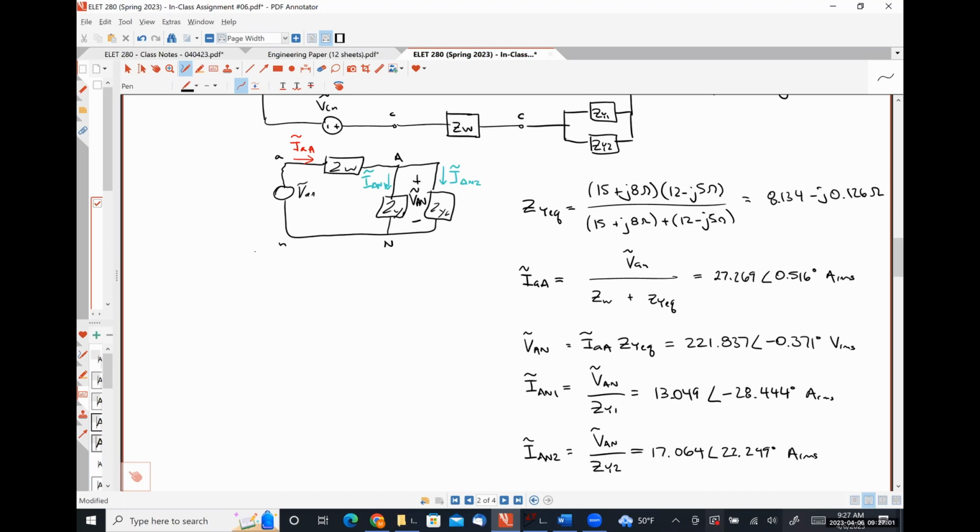So in order to solve for the phase currents in the B phase, what would I do? Subtract 120 degrees. For the C phase, subtract 240. Absolutely right. Not going to bother doing it here. You guys are catching what I'm throwing.